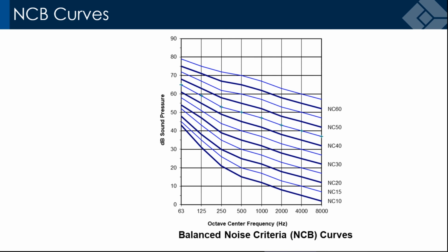Okay, just one note. When people tell you, oh, there's going to be foliage and grass and stuff like that, and it's going to attenuate all the noise, that doesn't work. Ground absorption does work at really long distances. Low humidity works. We talked about wind and temperature. And I'm to the end of my presentation.